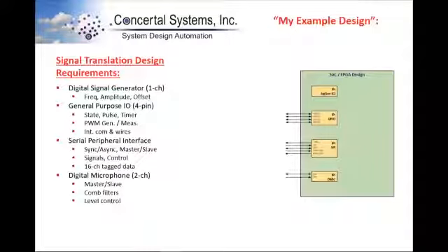And then the fourth IP is a digital microphone sensor input. It can operate in a master or slave mode. It has decimating comb filters, so it can accept a pulse density modulated single bit signal and output parallel words.